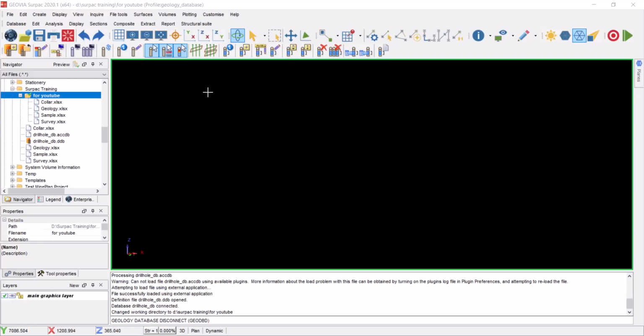So we're going to be covering the first step in any mining project, and in using any mining package, which is creating a geological database. Basically, a geological database is just loading the drill hole database inside the software, and the software will be able to recognize the location of these drill holes and the different intervals that were intercepted in the field, so the different lithological layers that were intercepted.